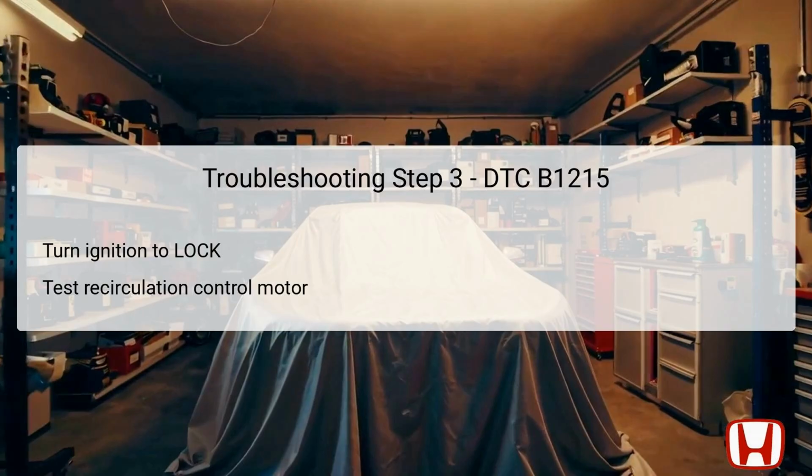the DTC. Step 4 focuses on isolating potential continuity issues within the circuit. The technician will begin by disconnecting the recirculation control motor's 7P connector, and then the climate control unit connector A, 28P. This disconnection allows detailed testing of electrical pathways between the components.